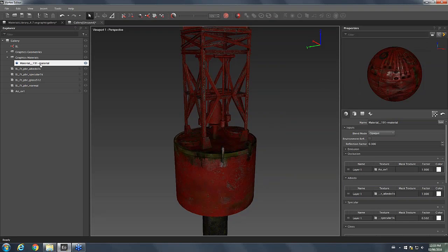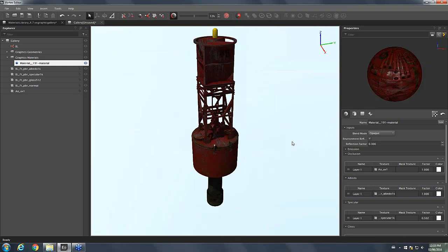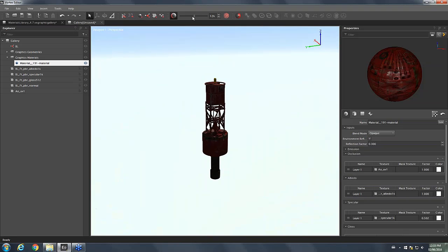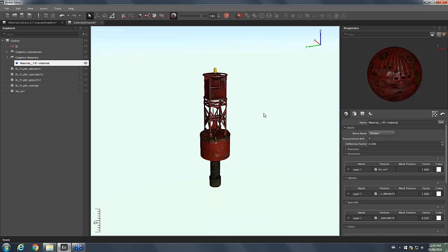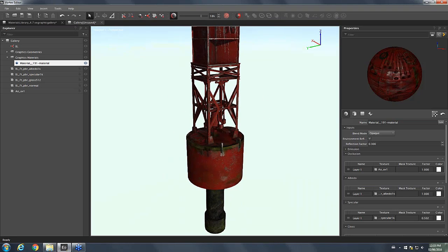So now we've got this, and now we've got all our texture put together. I also activate the environment reflection so that the sunlight will reflect in it. And then I put some sunlight in it so that we can see what the final model is going to look like in our scene. And then we can just play around with the time of day so we can see how the model will appear at different time of day.